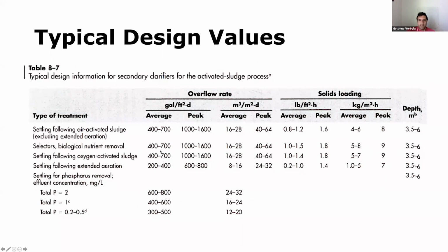All right, so you can use these values to make sure that your design approach is within the range of typical values for secondary clarifiers. But this is another area where you're going to want to consult the design guidelines to make sure that you are complying with the overflow rate and solids loading requirements, if stated.